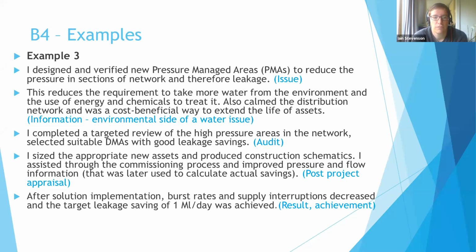I completed the targeted review of high pressure areas in the network with suitably sized DMAs with good leakage savings. So that's like a metered area. So there's the audit part of it. I sized the appropriate new assets, produced construction schematics. I assisted through the commissioning process, improved pressure and flow information that was later used to calculate actual savings. So that was an example of post-project appraisal. After solution implementation, burst rates and supply interruption decreased, and the target leakage saving of 1 megalitre a day was achieved.